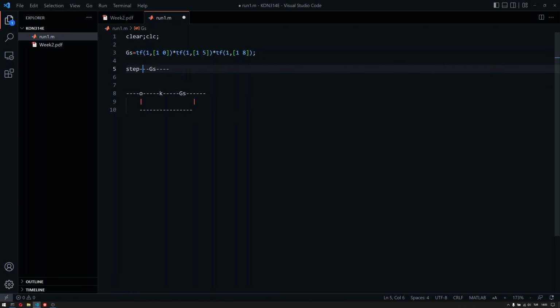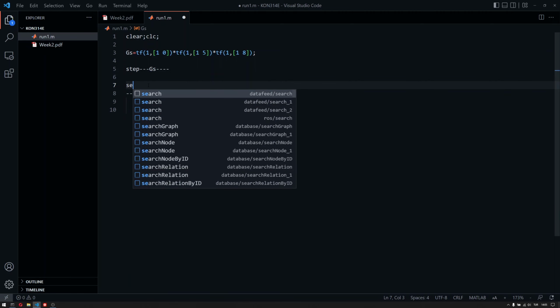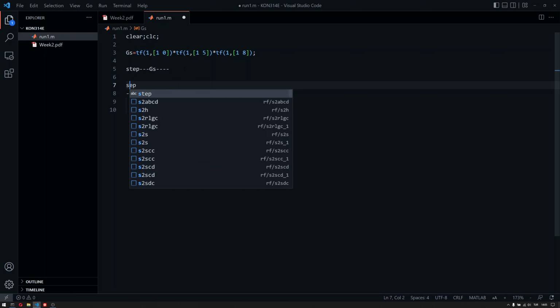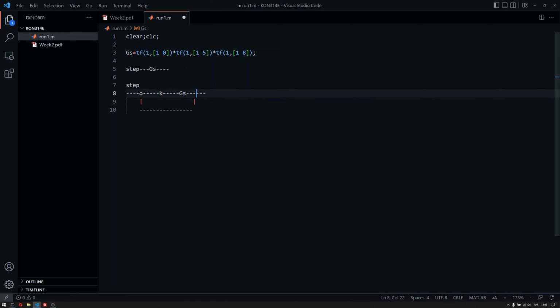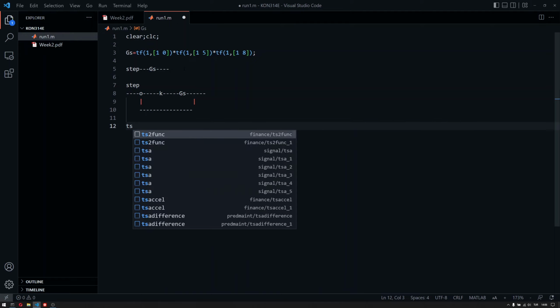So the amount of time that is needed to transition from the transients to the steady state is a measurement of settling time. And we will have a controller, a closed loop transfer function, and if we apply step to this structure, we want to have a certain settling time assigned to it. So the overall transients should satisfy a certain settling time.